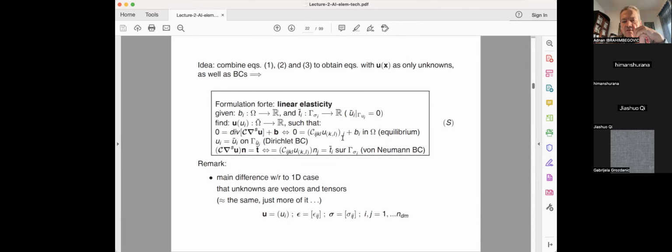So no wonder that many illustrious books had to be written about how to solve these second order partial differential equations for very special cases. Again, these are books of a couple hundred pages or even more, and there's not a tremendous number of examples that you can solve with such an approach. But still, there are a certain number that are always useful for testing the performance of your numerical solution. Then you can also impose your displacement, and you impose your stresses, which are expressed in terms of displacement. This is the way you define the strong form of the boundary value problem for linear elasticity.